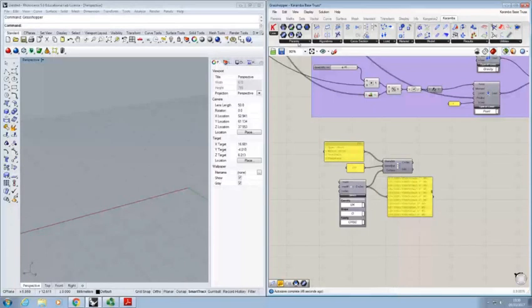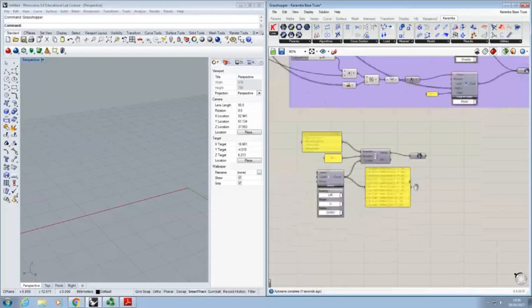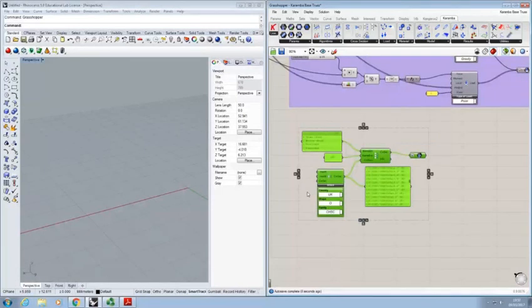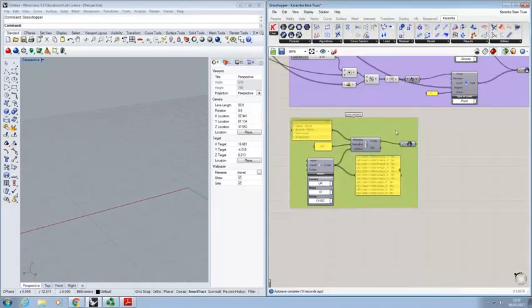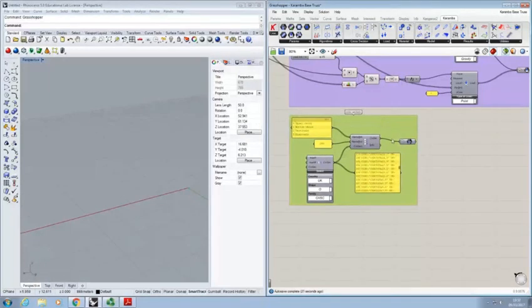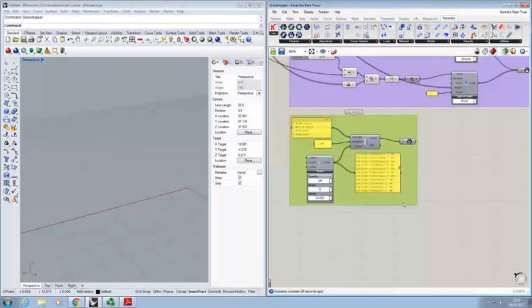Now again, let's assemble the cross-sections. Just go cross-sections in the parameters, plug that in, flatten the list as before. And we can create another group here. So cross-sections. Yeah, so all that happened here is that we've selected the 610 CHS for all the elements, essentially.